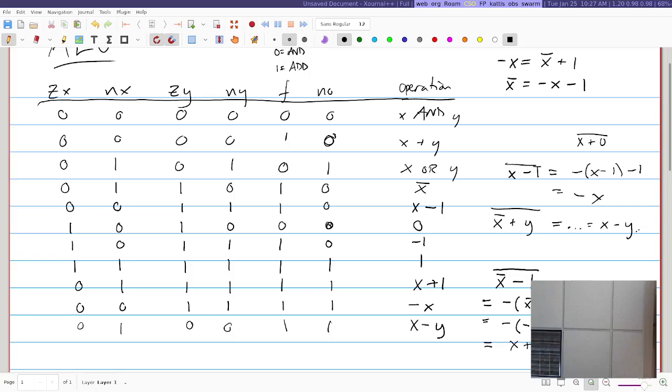That's a pretty good list of fundamental operations that we can instruct the ALU to do, just using these basic building blocks of the AND gate and the addition circuit that you guys are building, plus the ability to selectively invert and zero stuff out. And all that combined gives us a lot of flexibility. So, yeah, nice. Any questions?